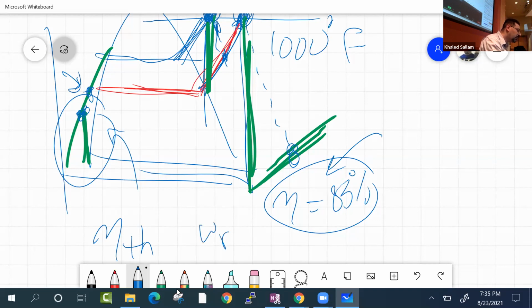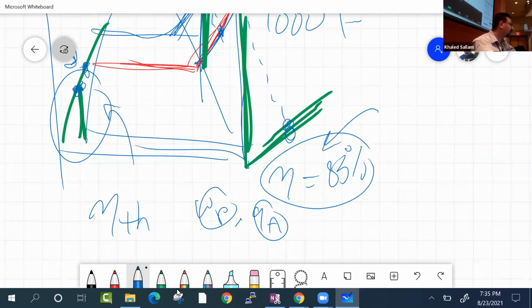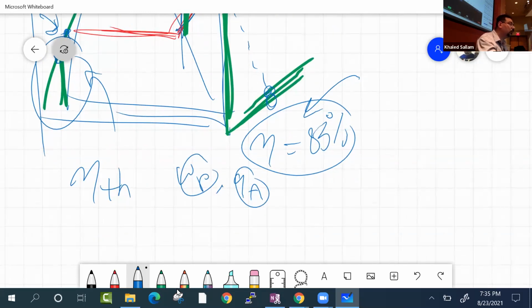Well, it will change work pump a little, and it will change Q added a little. I do the calculation, get those two, calculate eta thermal, and show that eta thermal for the whole plant changed only 5%, for example. Then I'm saying, okay, that design is okay. Less than 10%, we are fine. We are not designing a NASA mission to Mars. So if it's 10% or less, we will write the number and say that the change is less than 10%.